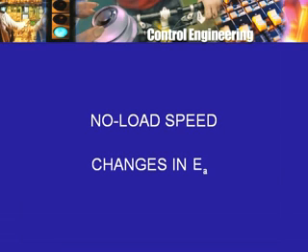Besides that, changes in the load torque, especially on the higher side, this is again something one has to look into. So far we looked at what happens when one of the things which we assumed in the design, TL, is no longer at that value, no longer 30 Newton meters, but 10% greater maybe, or 20% greater, or no load case, so 0.